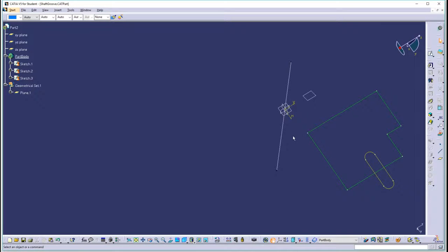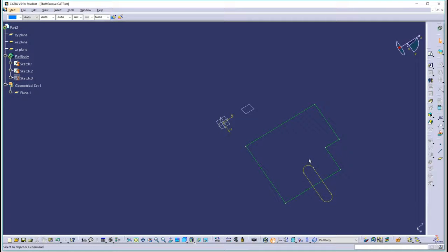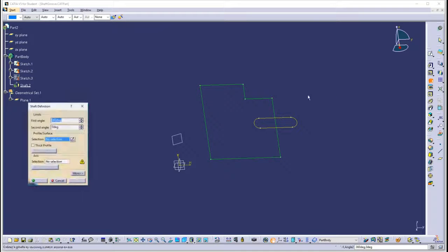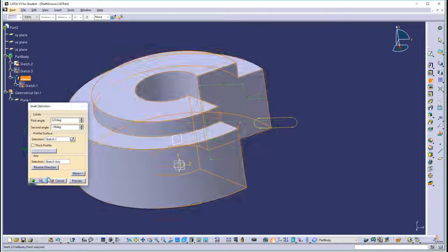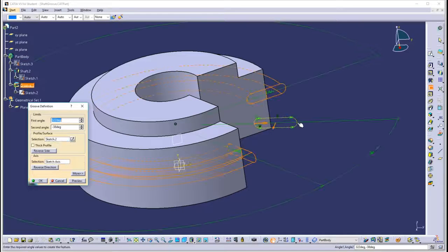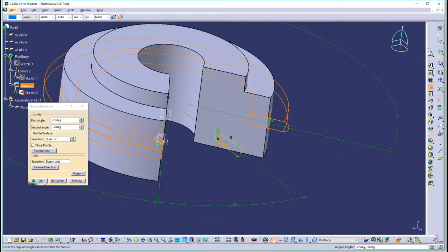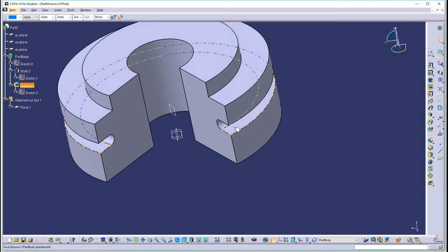Now I am going to cancel this, and we'll delete that shaft. And now let's do a groove. Let's hide this. Let's put the shaft back in, the default, all the way around. Let's make it come about here and say OK. Now we'll make a groove using this profile. Let's select the groove icon, select this, and we'll say OK. Now that removed material all the way around.